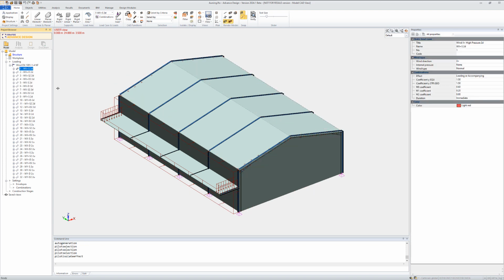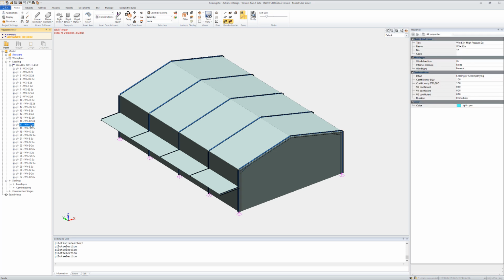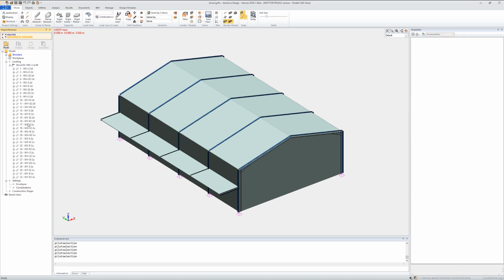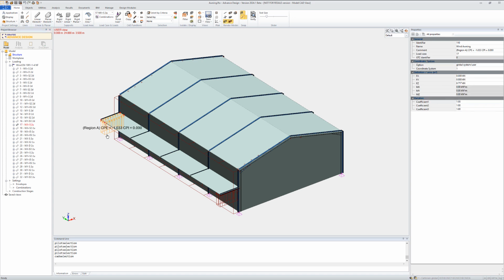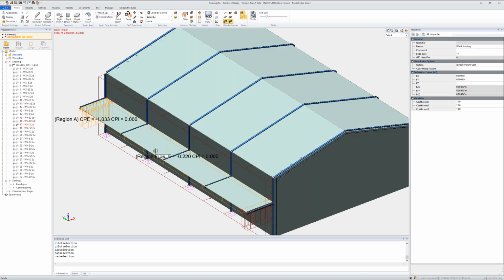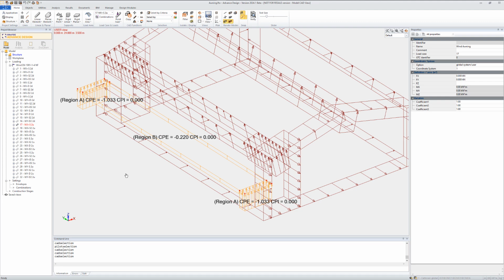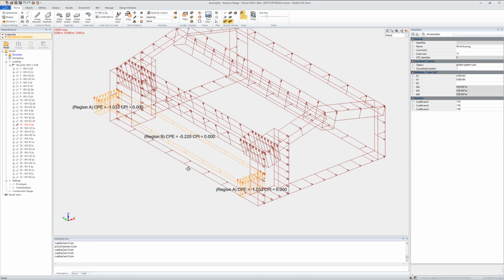the various outcomes for the awnings, because the force can be descending, so you have a descending force on load area 2, which is the awning, and then we will find at some point the same load case but with an ascending force. So this was the case with the descending force on the awning, and then you will have the ascending force on the awning with a high pressure coefficient. And we can see that on the awning we've got an A zone, a B zone. So we got A zones on the sides and then a B zone in the middle. So this is a proper wind generation on an awning.